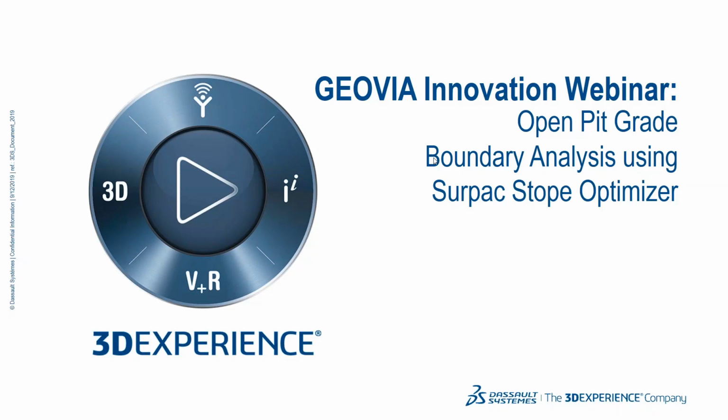Why use a 20-metre slicing interval? Well, really, just looking at the ore body, that could be one of the parameters you might like to investigate. You know, what's the minimum strike length, for want of a better word, of an ore block? And you can play around with the slice intervals. I use 20. I could equally have used 30, 50. You know, it all depends. It's governed by the ore body that you're evaluating.